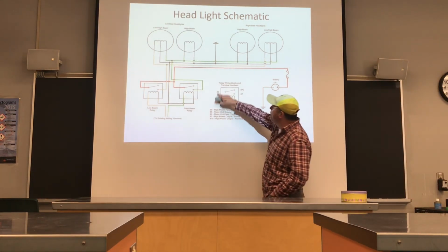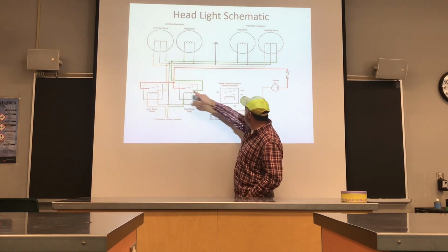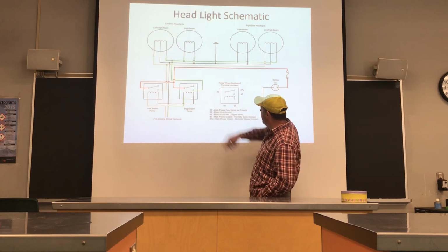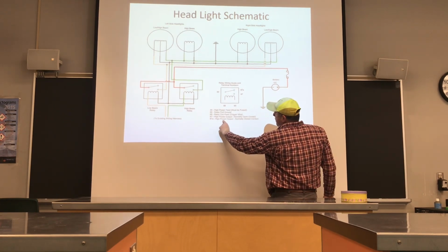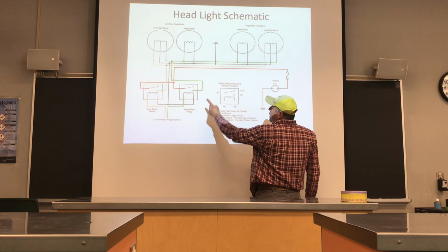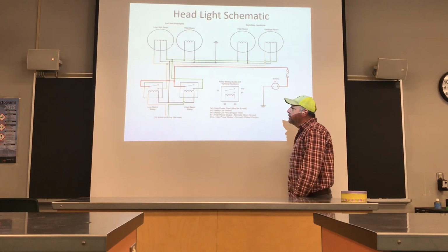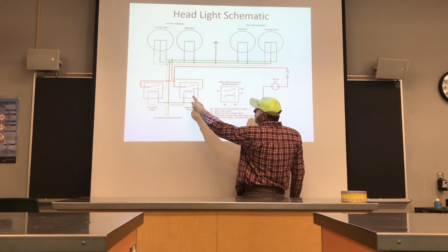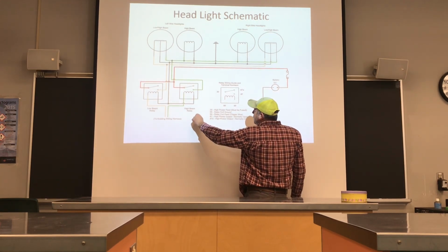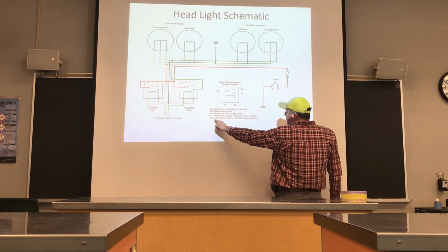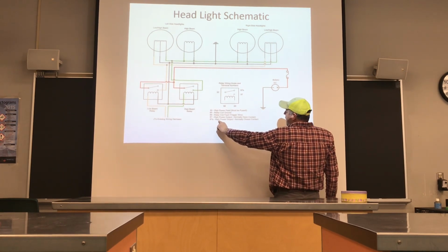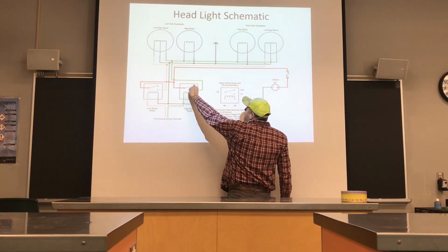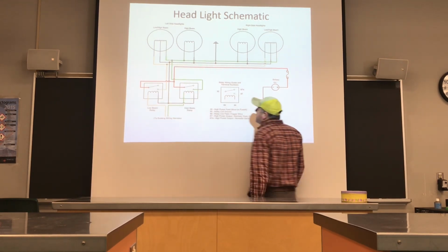Here's an example of what we're looking at over here. So 87A on both relays, they're telling us high power output, right? So it's probably going to be, say, a 30 amp. Say we're going to send 30 amps to our lights. 87A, high power output, normally closed contact, so you can see there's no wire attached to 87A.